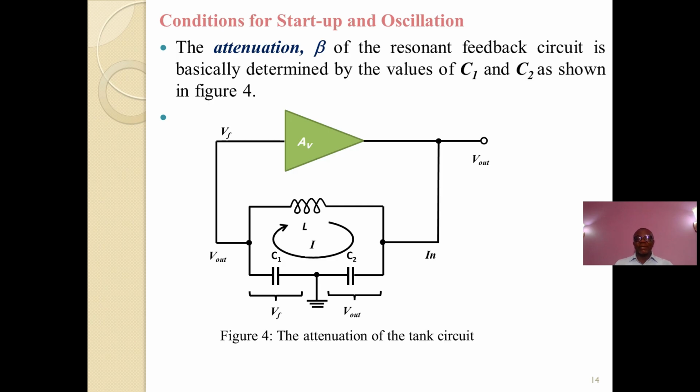Because it's a feedback circuit, the feedback goes through the LC circuit back to the amplifier, while at the same time giving an output. So both the phase shift equal to 0 and the gain being unity all happen in this circuit we are seeing here before going back to the amplifier.